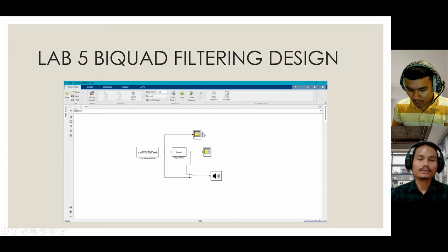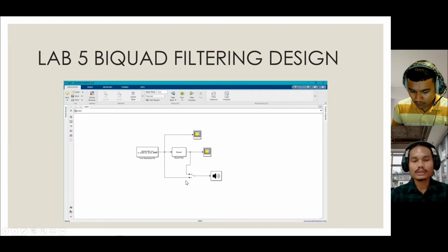We set up two spectral analyzers, one for the unfiltered noisy signal and one after we use the Butterworth filter. Then we set up switches, whose function is to switch between the direct signal and the filtered signal. We use one audio stereo output. After we run it, we can simply switch between the raw signal and the filtered signal. So we need to construct the circuit below.